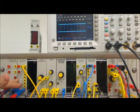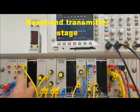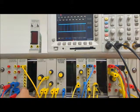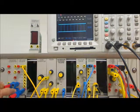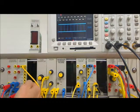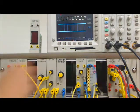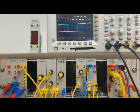For your convenience, I've already wired up the signal according to the block diagram in figure 5. We'll now look at some of the signals and make various adjustments and discuss them as we go. Starting with the sequence generator, which is clocked from the line code encoder output. The line code encoder is clocked at 8 kHz from the master signals, and 2 kHz is output to the sequence generator, which acts as the bit rate for the system, 2 kilobits per second.